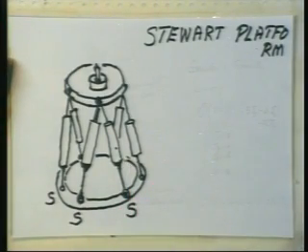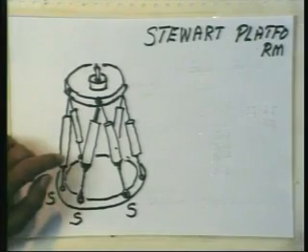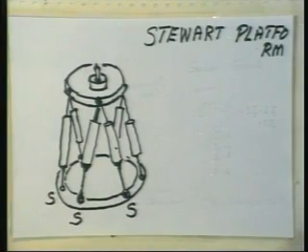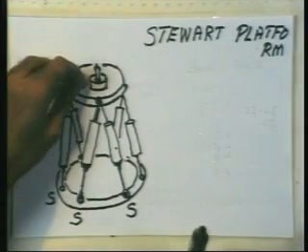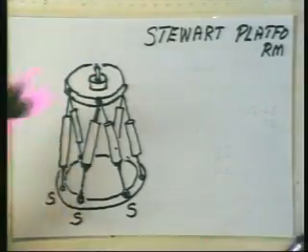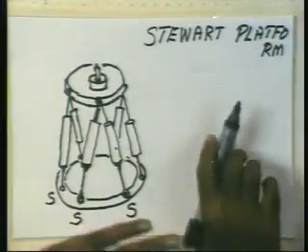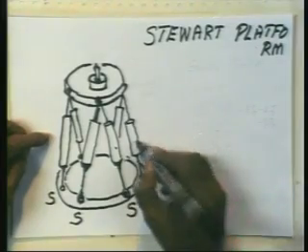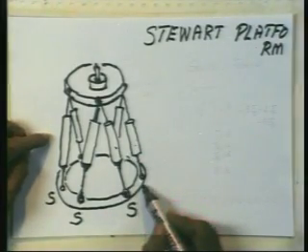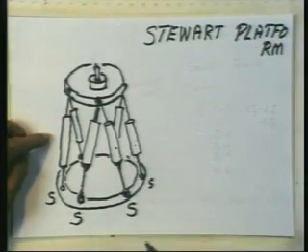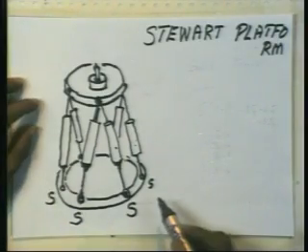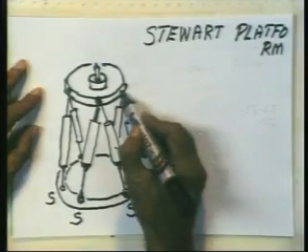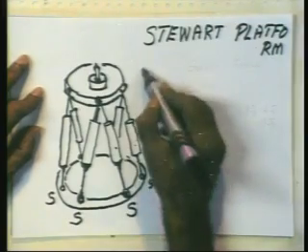Reasonably fine. On top of it I have kept a motor with a drill on it. In the end effector there is a motor with a drill. Imagine it's a drill. Now the top plate can tilt and move with respect to the bottom plate as these actuators move. There are 6 actuators. These 6 actuators, as I said, are connected to the bottom plate through spherical joints, the ball and socket. At the top, they are connected through hook joint.